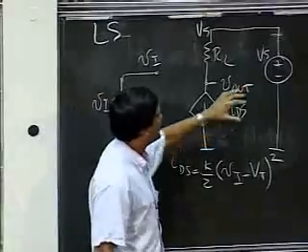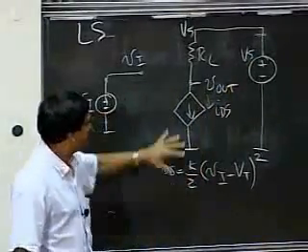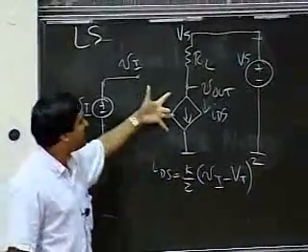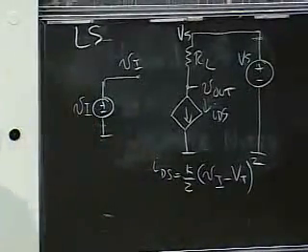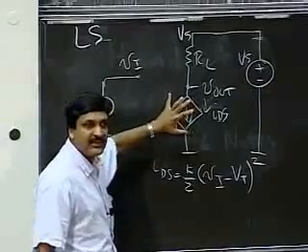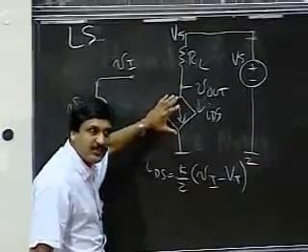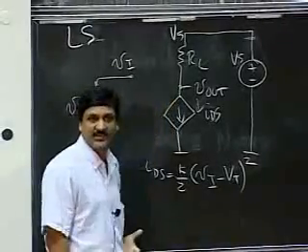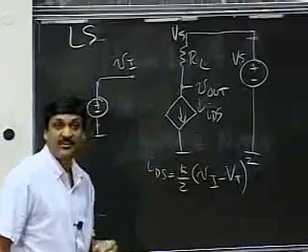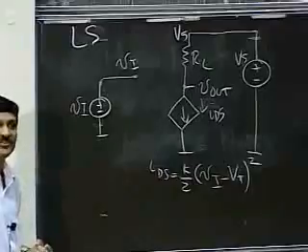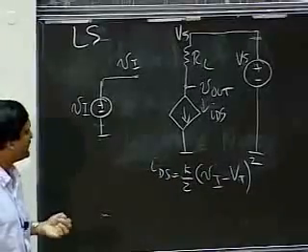In other words, here's a VS source. Here's a dependent current source. Let me replace them with their linear equivalent circuit models, in other words, with their corresponding small signal element models. And I'll show you what those are in a second. The resistor has a corresponding small signal element. The dependent current source has a corresponding small signal behavioral element model.